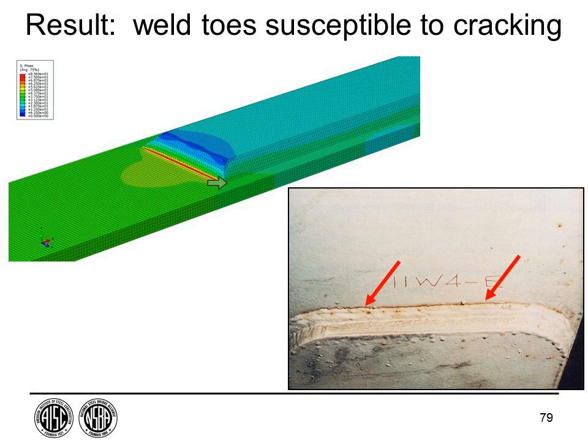But again, notice along the length, there's really no stress concentration effects. And so I wouldn't spend time inspecting here. And in fact, the fatigue category along the length is category B, while at the end, it's category E or E prime, because that's where the stress effects are the greatest.